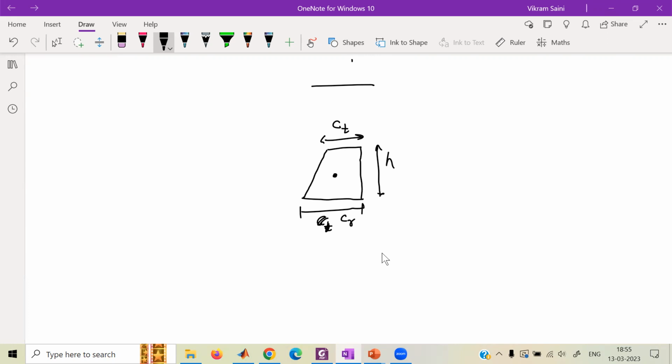What we have at hand is SV. We found that out. Just to remind everybody what we are doing here: we said that the aircraft should have certain stability properties in the directional case. We were given a number, C N beta. That is the desire that the airplane should have a certain stability. That was the specification. From that specification, we found out how much area we should take for the vertical tail.